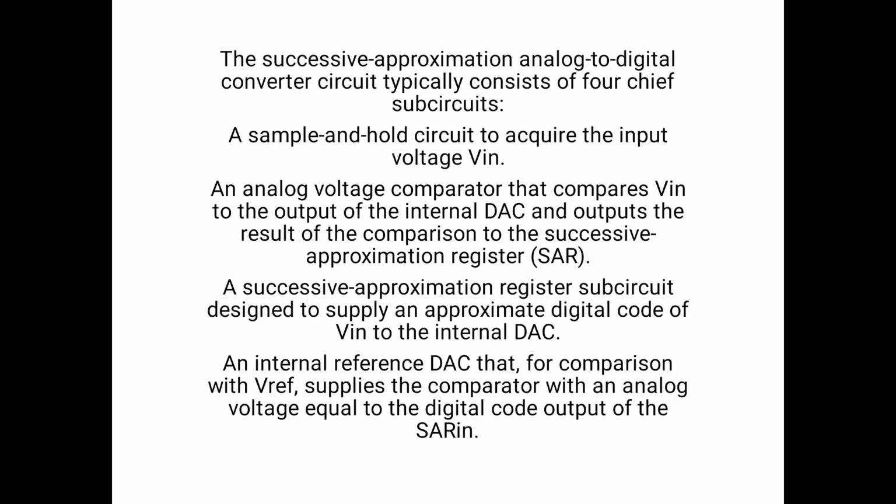SAR full form is Successive Approximation Register. A subcircuit designed to supply an approximate digital code of Vin to the internal DAC. An internal reference DAC that, with comparison to VREF, supplies the comparator with an analog voltage equal to the digital code output of the successive approximation register.